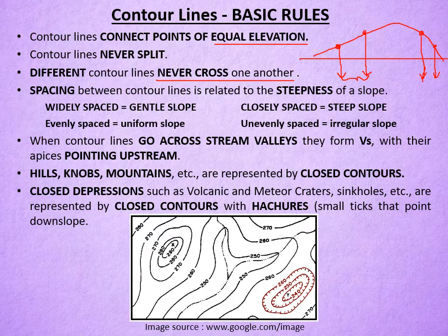So on this side the contour interval is that. So you can get an idea that whenever the slope is gentle, for this hillock, this side having the slope is gentle, this angle is low, whereas on this side this angle is relatively high compared to this one.